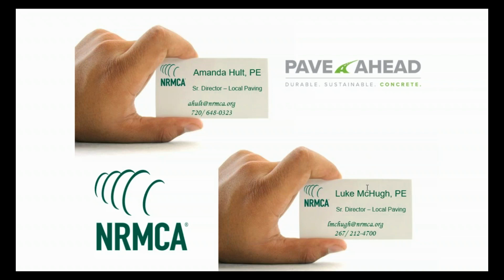And the next question: there is significant discussion that centers around joint treatment, i.e. sealants, fillers, or left open. Is there a current consensus? Michael, in the presentation we did talk about sealing, with some of the main reasons being to keep water and incompressible material out of those joints.